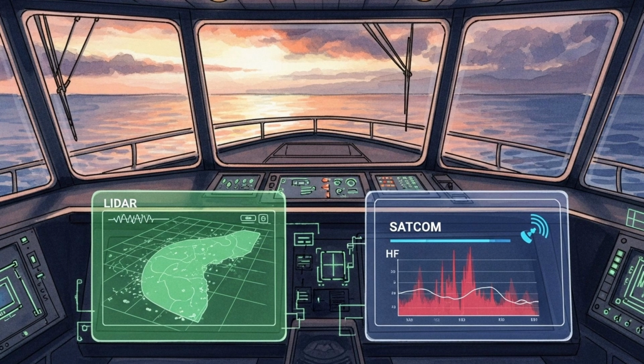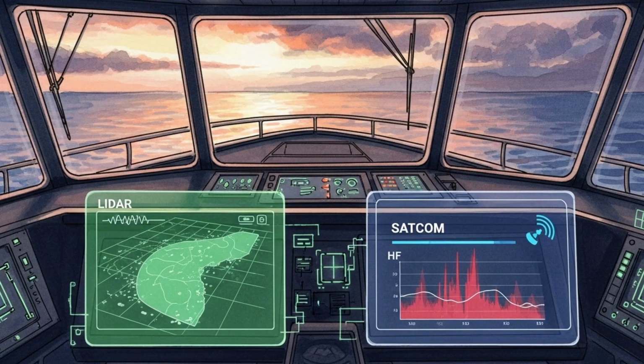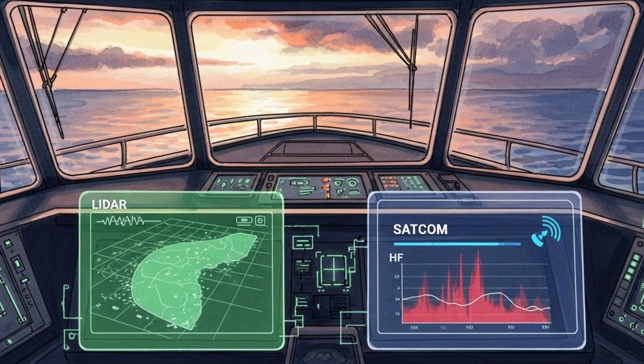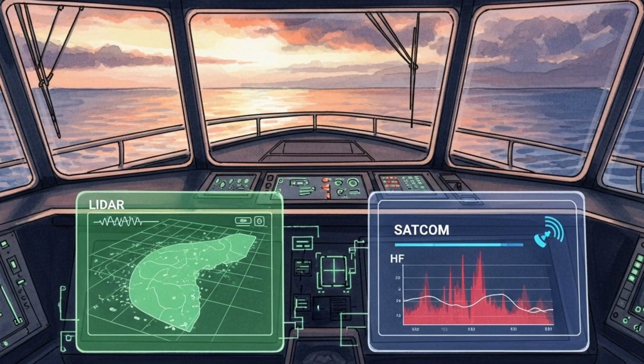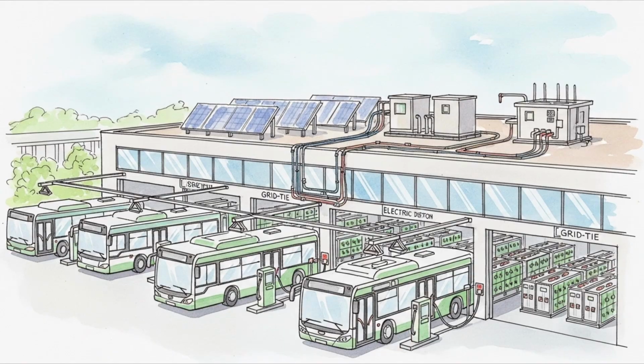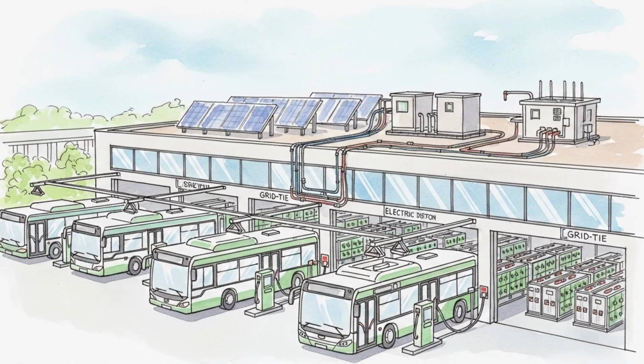Procurement rules incorporate space weather resilience. New transformers include thermal margin and monitoring for neutral current, winding temperature, and dissolved gas. New substations include neutral measurement, harmonic measurement, and communication to control centers.